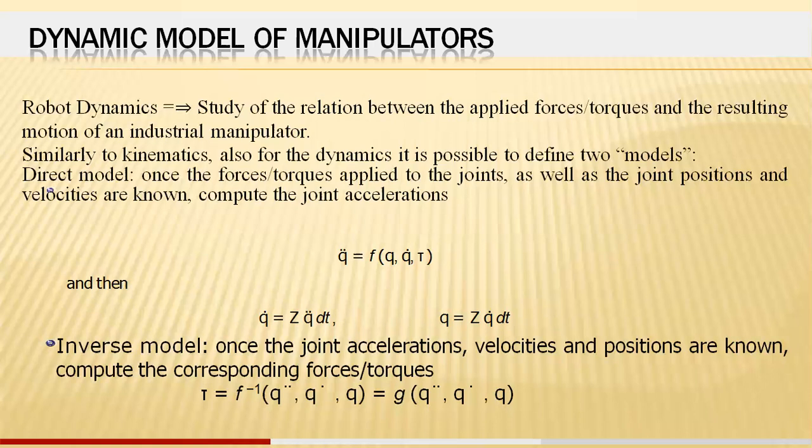And secondly, we have to analyze that upon moving with respect to a particular theta, the robot end effector may enter from one coordinate frame to another coordinate frame. This phase of actions we have clearly observed in our kinematics of machinery, and kinematics of robots also: forward kinematics, inverse kinematics, based on the already existing position. If a further theta is given to the particular link, it will enter into another coordinate system.